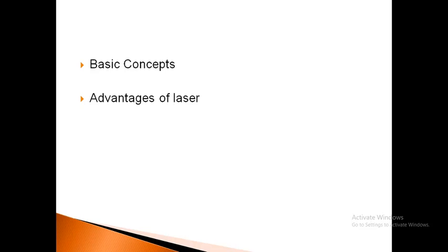And the next point is that the reference of the laser beam is always 100% straight. This is the most important advantage of laser: the laser beam is always 100% straight. Next, by using the laser, it is possible to document the measurement results as PDF and transfer them to a PC. And it has the ability to compare the measurement results with the ISO standard, which is used for machine tool measurement.